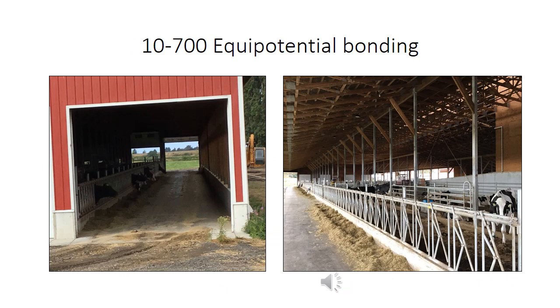And in this photo here, we have a barn housing livestock. The stanchions, in other words, what the cows put their heads through, all of those stanchions will require bonding of some sort or some type. The problem with animals that have hooves is they actually make contact to the ground in 5 points. In other words, 4 hooves and what's called a snout.